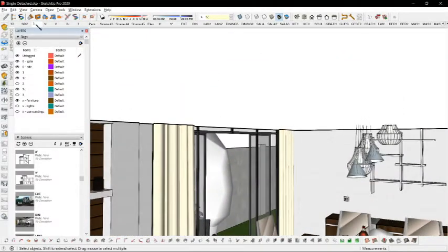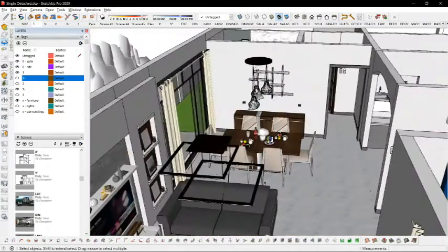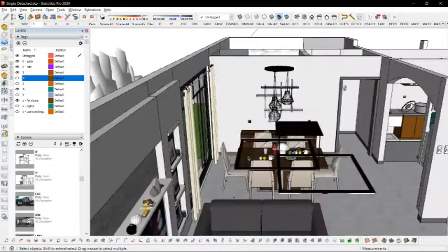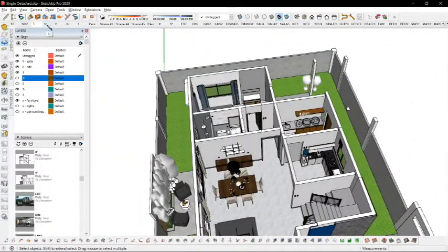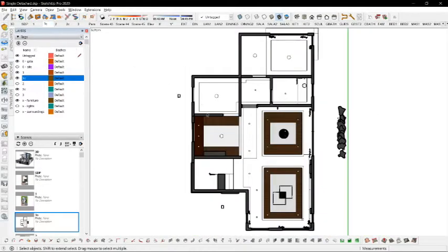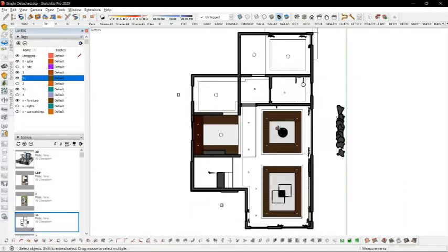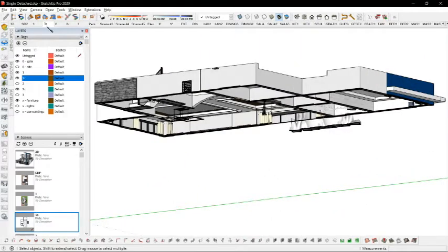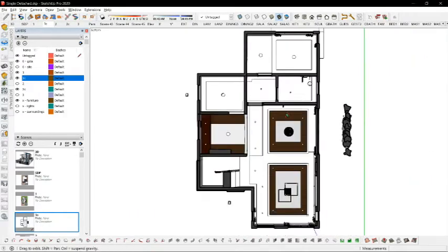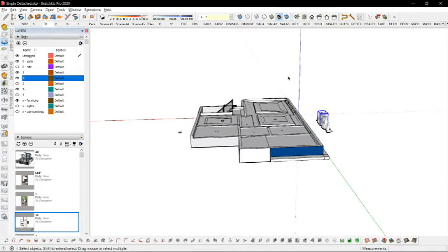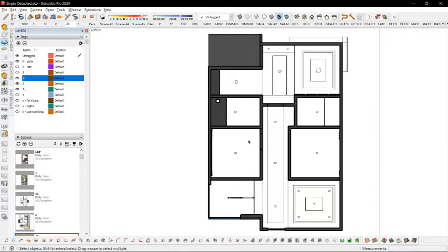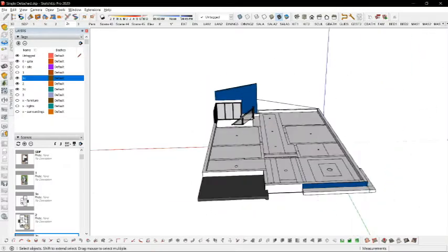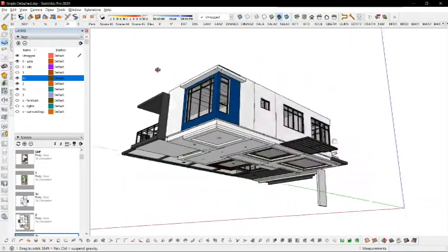So in my first layer, I turn off the ceiling and only use it when it's time to visualize the ceiling by going to its own layer 1C, which actually goes to the bottom view. So I could edit the ceiling from below. And then to 2C. So it's like a form of reflected ceiling plan, but it's just a section cut.